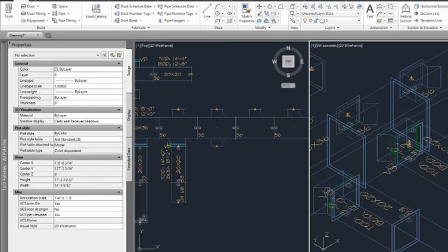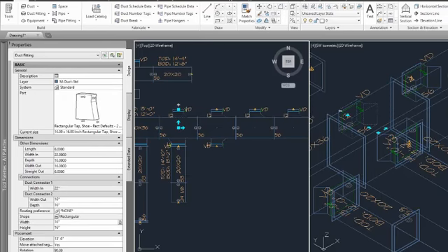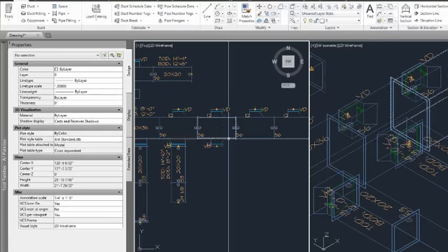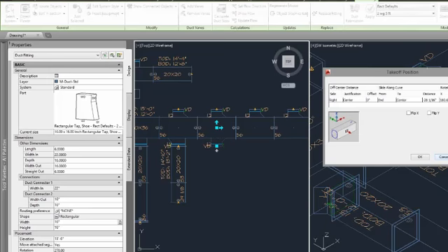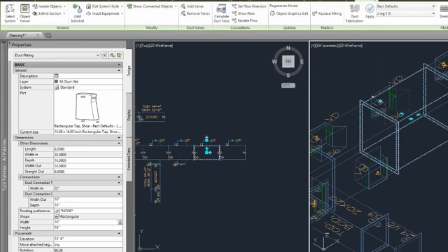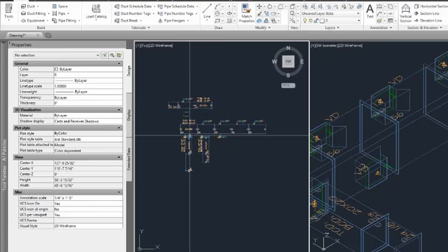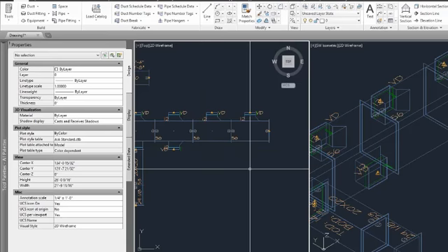If we look at each one of those, we can see that it automatically has the correct anchor on it right away because we get the takeoff position dialog. So manually placing your tap gives the correct anchor every single time, even when it's in the center of the duct. So some good tools to learn and understand. Make sure that you place your not so common fittings onto your tool palette for easy retrieval. Make good use of the anchor dialog. All of that will save you a lot of time.